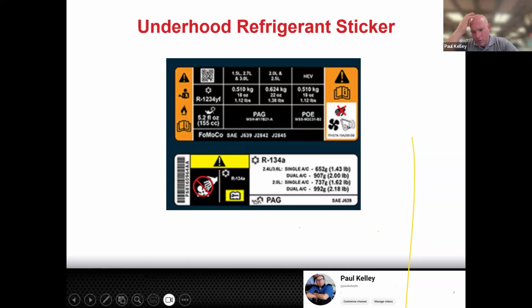So you can't use normal refrigerant oil in a hybrid electric. The technical reason for that is PAG oil is not very resistant to conductivity. It's a little bit conductive to electricity. In a high voltage AC compressor, first off, a hybrid or EV is going to have an electric driven compressor, and that's going to run on high voltage, probably 3-phase AC.